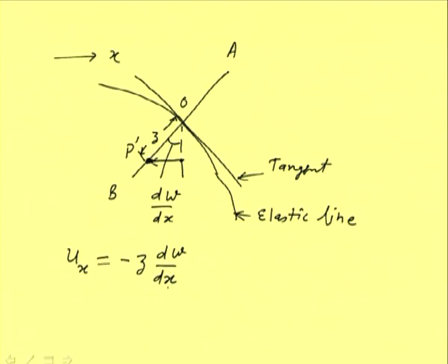So this is the displacement of the point P in x direction according to Euler-Bernoulli hypothesis. The displacement in the y direction, that is a plane which is perpendicular to the plane of the board or the screen, is 0. So when we are applying a transverse vertical load, there is no displacement in the horizontal direction, and uz is w. So this is the displacement field.